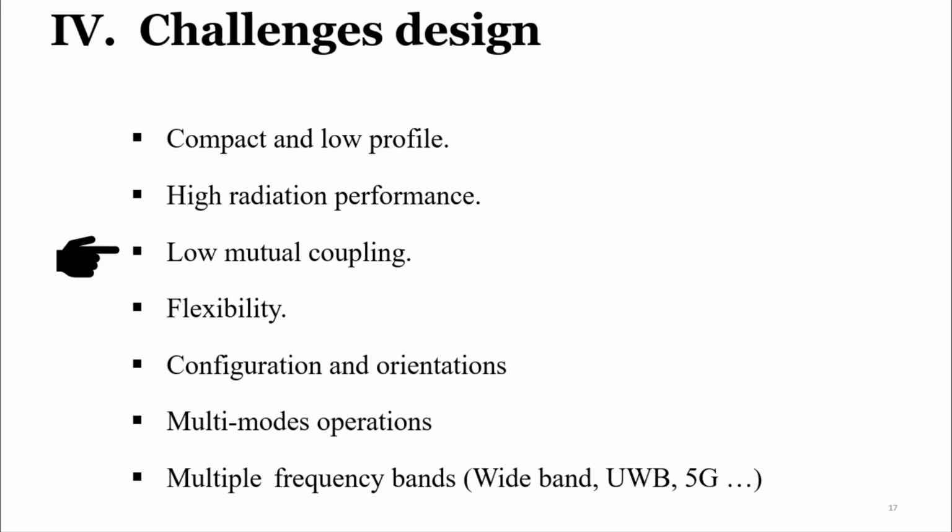Okay, so we have several geometries in the ground plane, and the third case we can talk about is the split ring resonator. Okay, so we have three popular methods used to decrease mutual coupling between radiating elements in array antennas, patch antennas, microstrip antennas, or coplanar antennas.